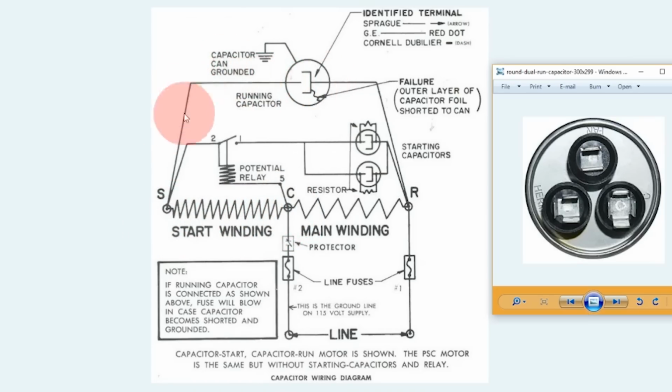Now, some of you may say, hey, I know for a fact that I see high current on a compressor when it starts up. So I think a locked compressor can cause a capacitor to fail. I think high current can cause the capacitor to fail. But you're reading on the common lead, the lead coming from the common terminal. Now, common isn't a winding. It's just a point in between run and start. So when you read current on common, what are you reading? You're reading run and you're reading start. You're reading the current on both of those lines, right?